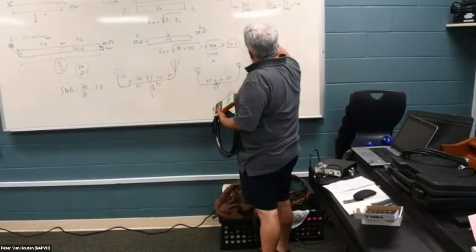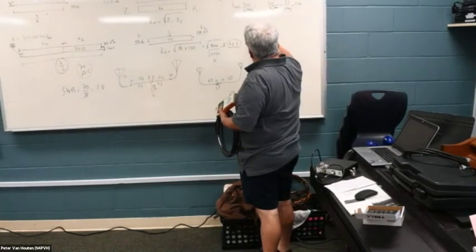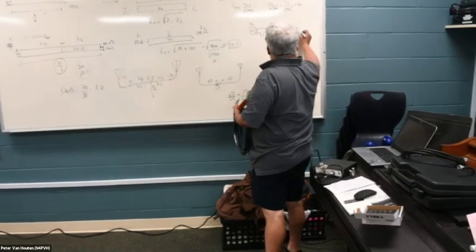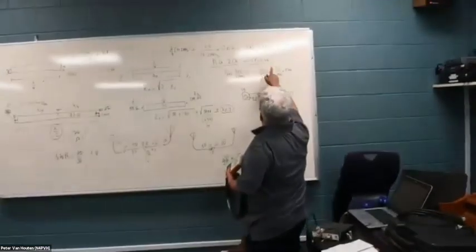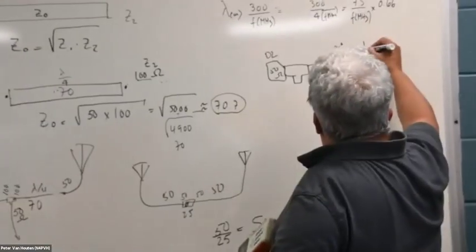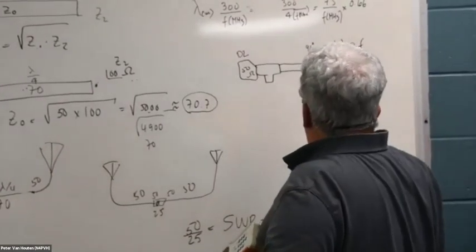Here I put the 50 ohm dummy load. And here I connect the line that I'm trimming, that I'm cutting to make it 90 degrees or 1/4 wavelength at the frequency that I am intending to.